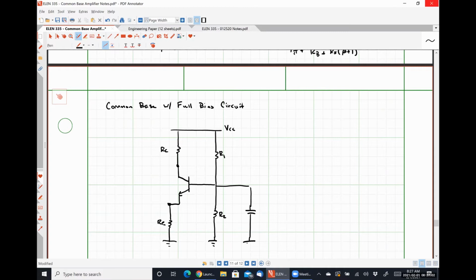So in order to do that, I'm going to put a capacitor explicitly in parallel. I'm going to call this guy CB with resistor R2. I could put the capacitor between the base and VCC as well if I wanted to. It would have the exact same small signal effect, right? So for large signal analysis, CB is an open circuit. My bias point is well established, nothing to screw with too much.